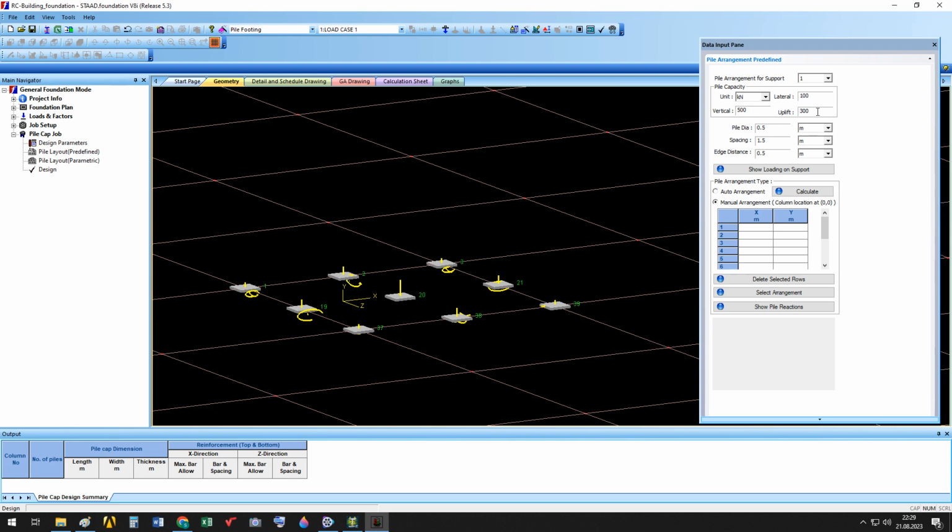If any tension vertical force acts on the footing, this will try to pull the pile from the soil. So against that, the pile shall also have uplift carrying capacity.